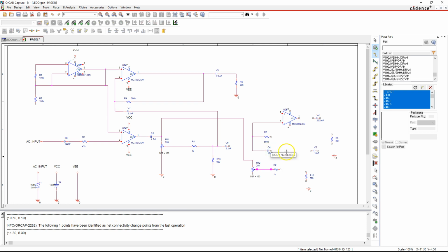Then this capacitor gets connected to this one. Make sure to split that connection with this resistor here. Now it's a little crooked, this connection, but that's fine. And there's a resistor coming out here, just click and connect it right there. Next, put this output into the capacitor and put the capacitor into this resistor. This will be our output node, and you'd use your net alias to name this node as well.